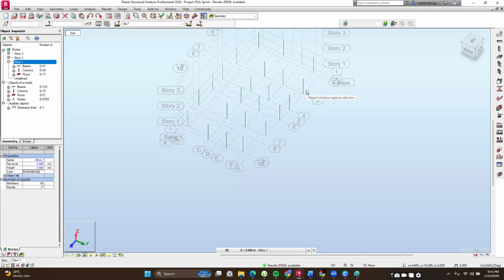So we may say that for these interior columns here, we can design for the worst case scenario. For those columns that are within the worst case scenario, we are going to assign them that particular section. And since it's the column we consider worst case scenario, if we have a section that passes for that column and rebar, then it means that it is going to be safe for the other columns.